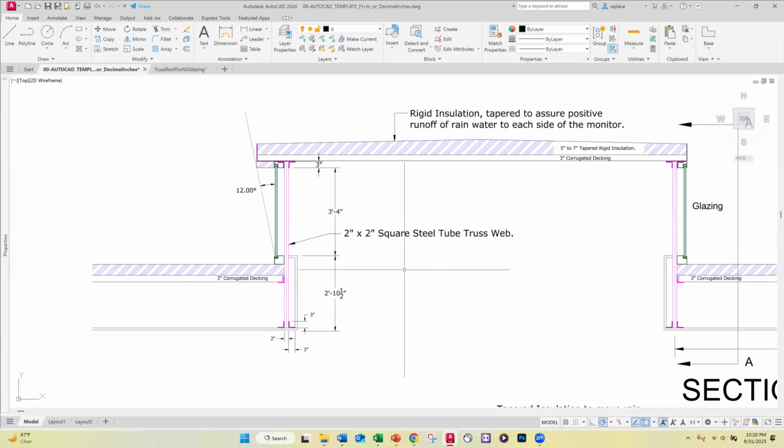In some cases, like for the chord members, it might end up with a fairly thick wall, but to first order, your engineer can tell you what the wall thickness needs to be to handle all the various forces that are going to be propagating through your structural system. And your engineer will say, well, okay, certain parts of this need to be 1/4 inch, some parts 3/8 of an inch thick, some parts might even need to be 1/2 an inch thick.